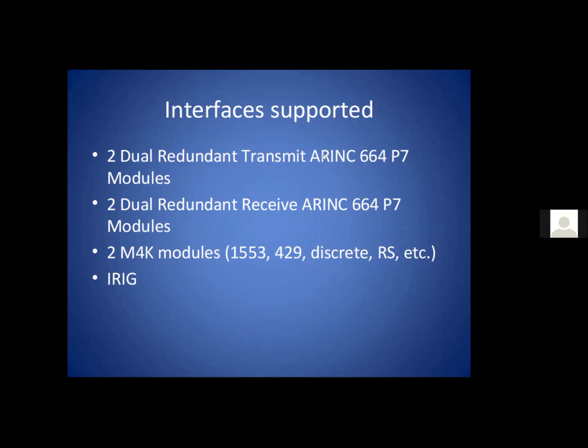Meaning that we time tag on receive, we time tag all messages that come in. There are two kinds of time tags that can be used. One of them is after reset, we start from 0 and then keep counting up. The other is an IRIG-based time tag. IRIG is taken from a satellite, so you need to have a receiver to get the IRIG. And then we'll attach to each message the IRIG time.